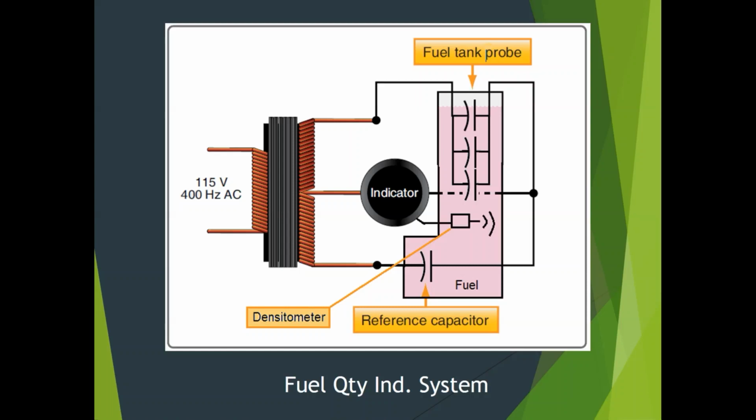be in open air, except for when maintenance dumps the tanks and needs them totally empty in order to go in for maintenance. Rarely will it be in open air. The whole point is we want it to be fully submerged in fuel all the time. And so that compensator wash line is going to spray fuel across it to knock crud off of those plates so that they can give an accurate reading. Okay? And then you can see I've also added a densitometer here that can tell us how dense our fuel is in order to complete that calculation to figure out pounds rather than just volume.